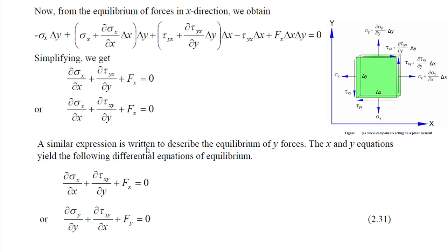A similar expression is written to describe the equilibrium of the forces in the y direction. The x and y equations are the differential equations of equilibrium. If you take forces in the y direction equal to 0, we can see four forces related to the stresses: sigma y in the negative y direction, sigma y in the positive direction with increase of stress, tau xy shear stress in the negative direction, and another shear stress component tau xy in the positive direction with increase of stress. And one body force will be there,